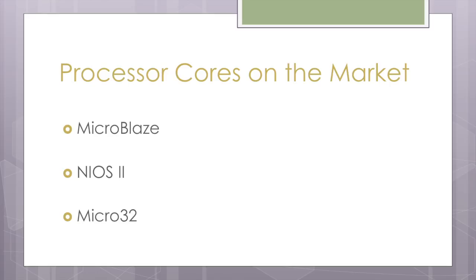There are 32 general-purpose registers, 32 external interrupts, and dual Wishbone memory interfaces. This softcore can run at over 100 MHz on low-cost 90-nanometer ECP2 FPGAs.